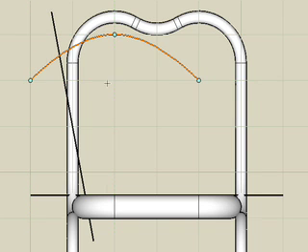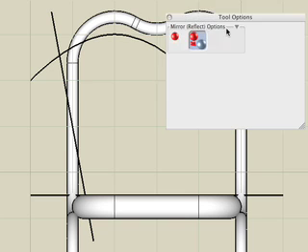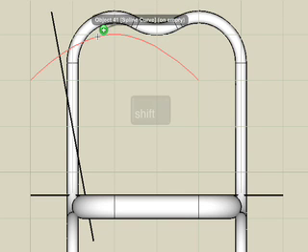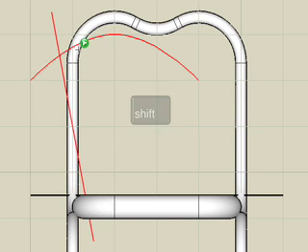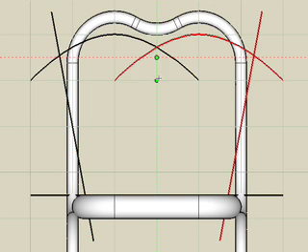And I want to take these two lines and maintain symmetry, so I'm going to mirror them over to the other side. So select the mirror tool, make sure you have the copy option selected, hold down the shift key to select both of those lines. Then when I'm ready to mirror, just simply click 2 points and they will mirror across that line.